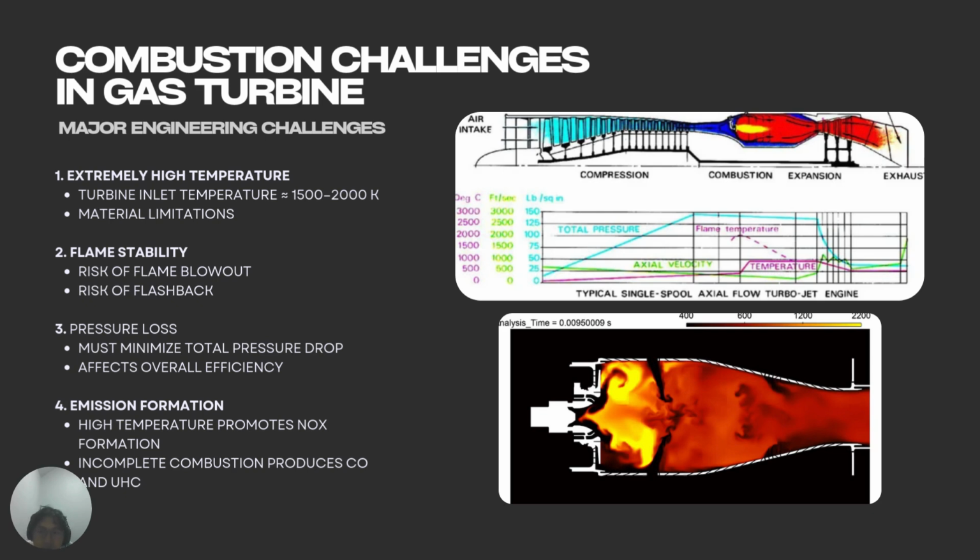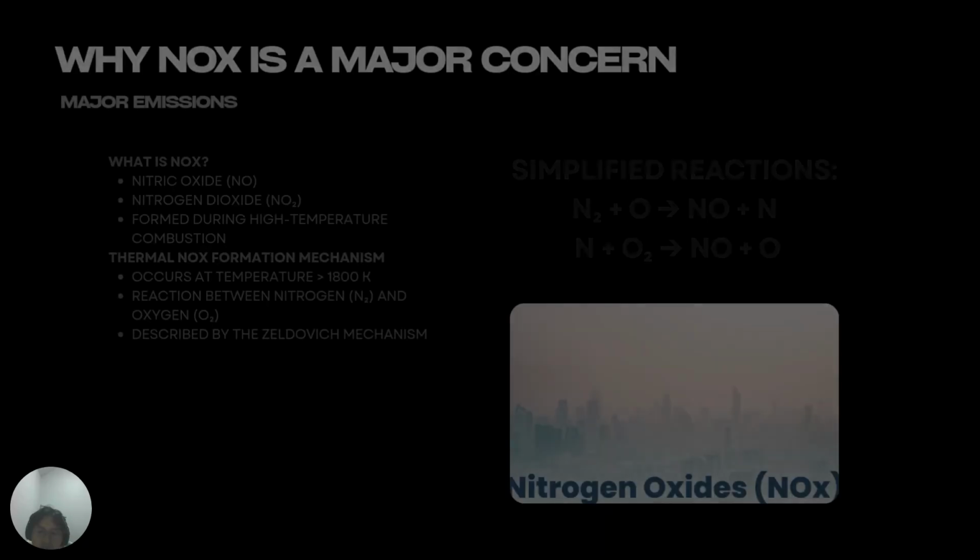Also, the pressure loss inside the combustor must be minimized to preserve overall cycle efficiency. Most importantly, high combustion temperature significantly increases NOx formation, creating environmental concerns.